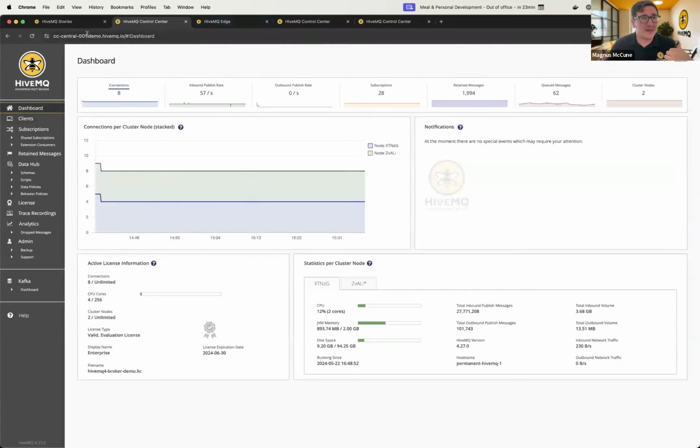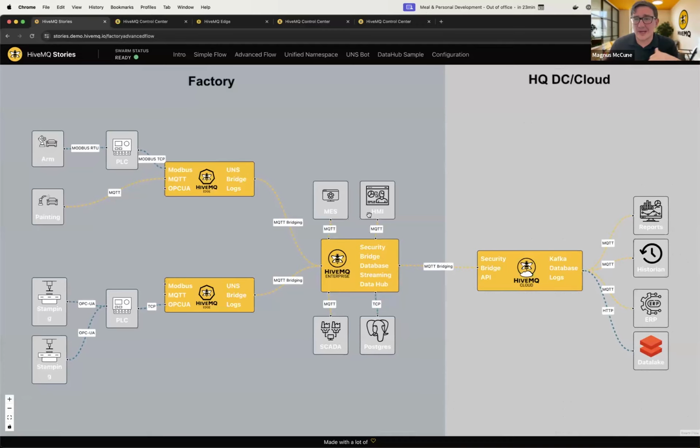One other thing that I want to highlight here is something we often see within these factories. Ravi touched briefly on MQTT Sparkplug, Sparkplug B, and those Sparkplug systems are really important. They're really critical because all of this stuff on the left may speak Sparkplug, and you may have a Sparkplug-native SCADA system that is doing a whole bunch of really important work. But as some of you may know, Sparkplug is typically encoded in what's called protobuf, and that's not really a readable format for an AI system.